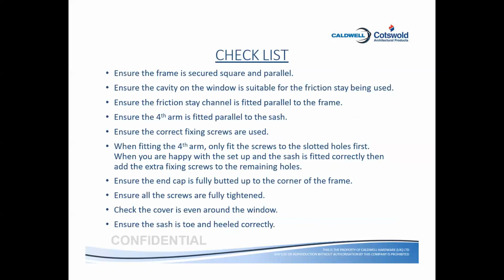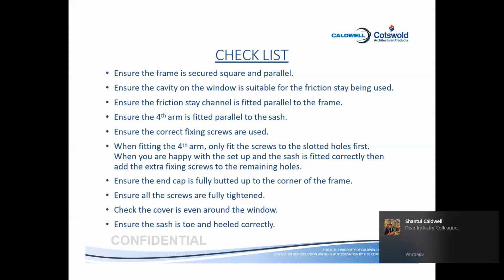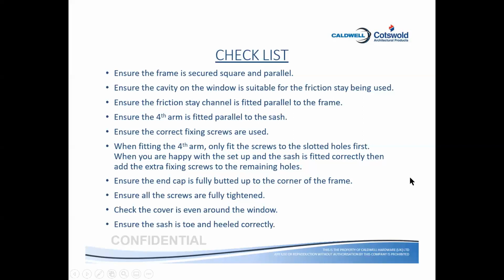Then coming to the fifth point of the checklist, ensure that the correct fixing screws are used. The screws which are recommended from the company are 5 mm diameter stainless steel screws, countersunk. These are the standard screws which the company is proposing to be used by their customer. I repeat once again, 5 mm diameter stainless steel 316 screws we suggest our customers use, with the countersunk, in all our friction stays.